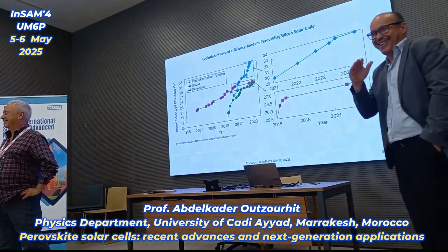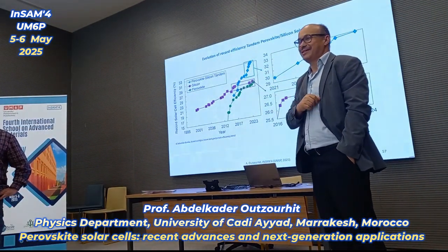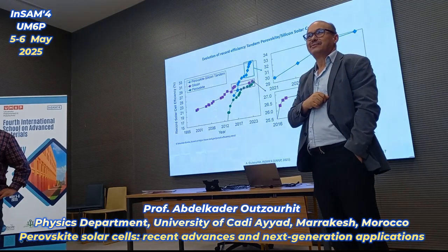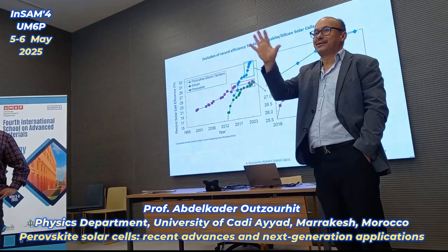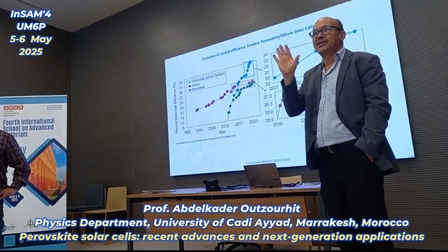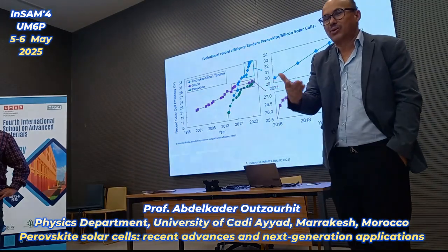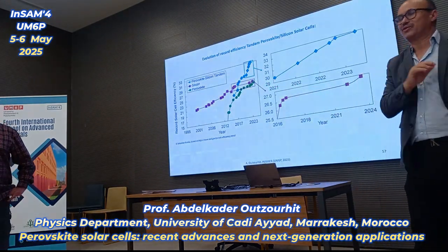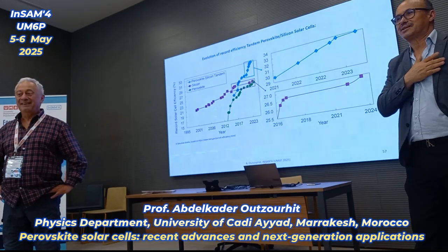Yes, you're absolutely right. Always under standard test conditions. The irradiance should be 1,000 watts per square meter and the spectrum should be AM 1.5. If you use STC, you have to cool the cell to 25 degrees. Okay. Thank you.